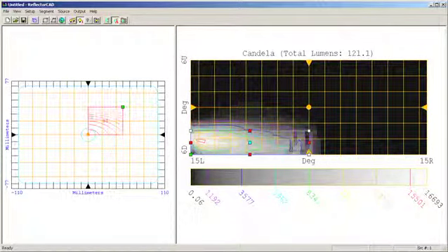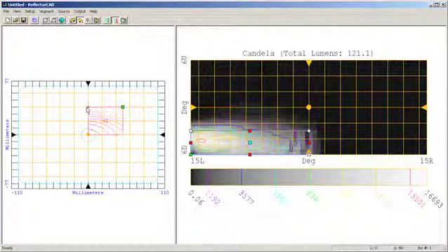Now, in the segmented area of the display screen, you will see a series of contour lines in the particular segment. What this indicates is whether this new segment is above or below the base surface that you've identified. We're ready to insert our next segment. I come up to my segment button, and I'll begin creating my new segment.